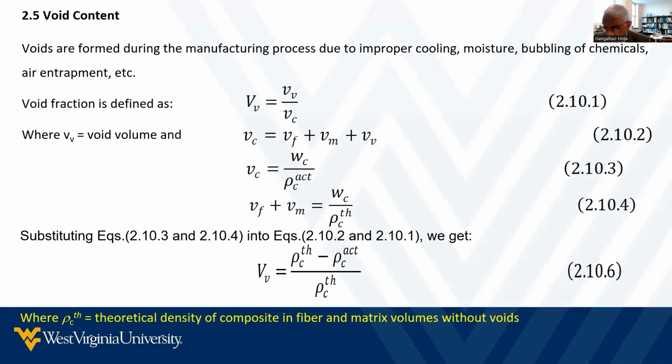The measurements are not easy to establish the volume fractions, but under the scanning electron microscope, we were able to measure the void content with a reasonable degree of accuracy.